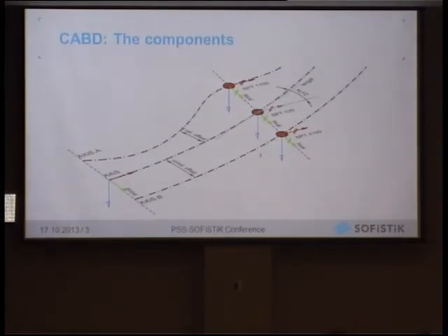Then you rotate around the local bridge axis by 30 degrees or whatever, and then you move 3 meters parallel to this axis, and you will obtain a point, maybe this construction or structural point 1110, without any additional hand calculations and additional source for errors regarding the geometry, so we can focus on modeling.